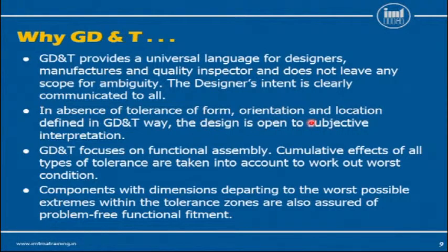Without GD&T symbols, the drawing becomes subjective. That means if three different teams are interpreting a drawing, three different interpretations could be possible without GD&T. Whereas with GD&T symbols, the drawing becomes unique and it conveys the same meaning across different teams, across different organizations, etc.